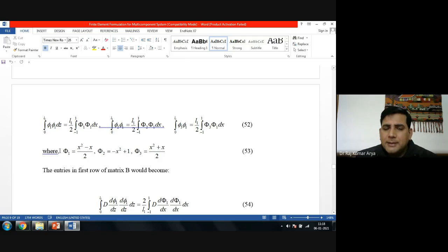And once you will change the limits there, these would be your new psi functions, x square minus x, x square minus x. This is between -1 to 1. These are given to you in any of the books or internet. Basis functions between -1 to 1. These are very well known actually. Or if not, you can do the derivation from my thing.